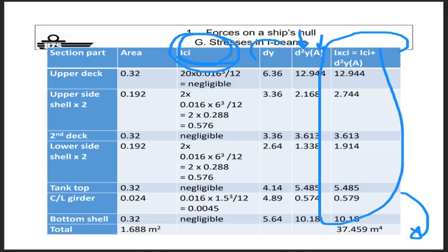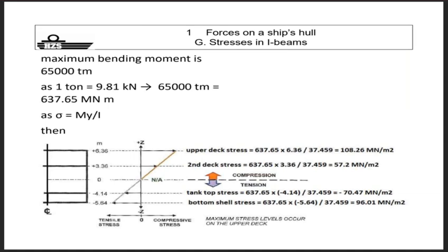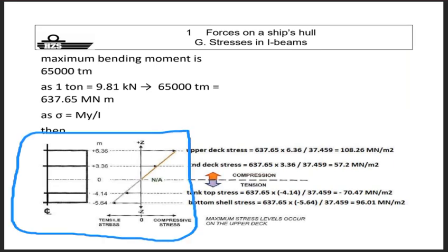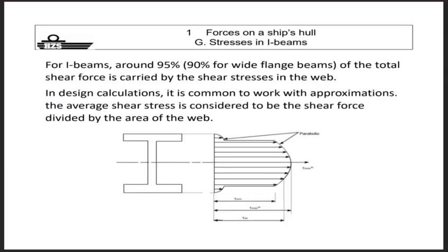axis. And then to visualize what I already visualized before, you see here the stress levels at the point where your bending moment is given, or for the point that you calculate it, and you can calculate it for every level. Now you tell me, yes, madam, it's a nice story for bending moments. Well, what about shear forces? I don't know if you recall, but for shear forces, contrary to bending moments, all the shear stresses are mostly concentrated here in the web.